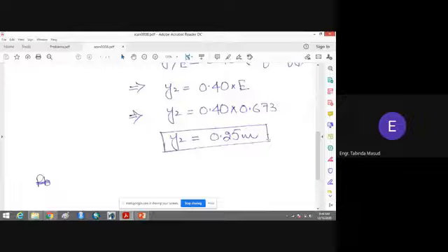because the dimensionless discharge curve may or may not be available to you, especially if you are in your examination hall. It is not an easy job to draw the dimensionless discharge curve at that time just to find the alternate depth of the flow. So I recommend that you must know both the methods, but if we compare, the dimensionless discharge curve is quite a simple method. There are no extra calculations, and you can easily get the value for the depth of the flow.